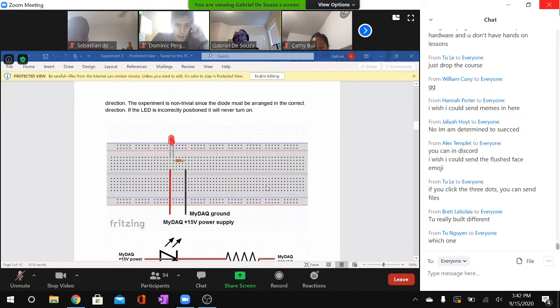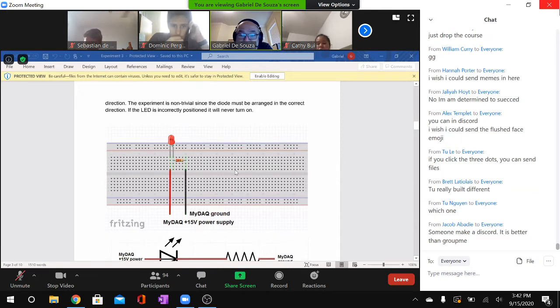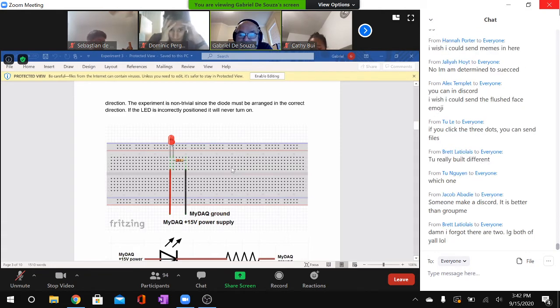Right there. Sorry. This here is called the proto board. And the proto board has wires under these holes that connect these holes. So this column of holes right here, these 5 holes are connected together. These 5 are connected together. These 5 are connected together.